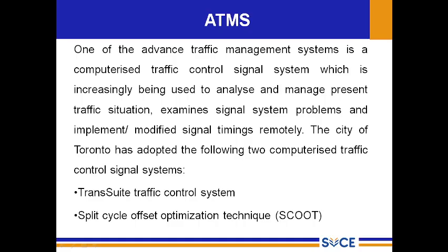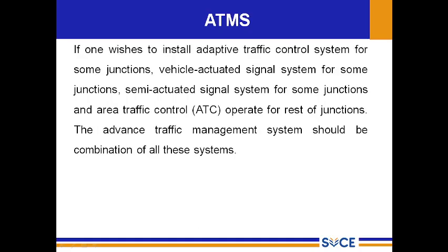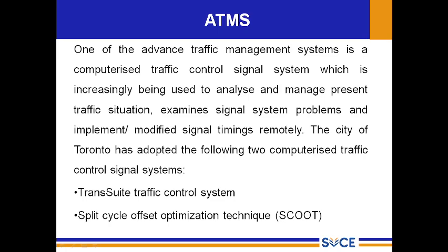In India, we usually use fixed-time signals where the green times are fixed irrespective of queue length. So what will happen? The people standing in the queue may get irritated and try to violate the red signal. This is one of the major causes for violation of red signals. Whereas in this system, there is a CCTV camera that automatically predicts the queue length. It processes the data through an image processing unit and adjusts the green time automatically and dynamically.